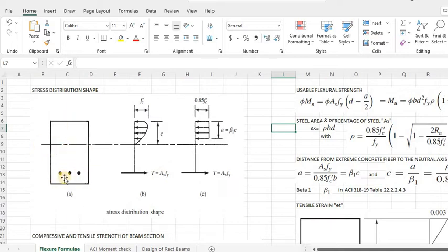So if this is your cross section, when they did some tests and analysis for internal forces, they found out that the concrete compressive side has this kind of shape, and basically this area here is your compressive stress or strength. For the steel, the tensile strength is basically, because in the concrete beam, the bottom, since the concrete doesn't have that good of a tensile strength, you need the steel. That's why we have the steel in there to take on those tensile forces, right?